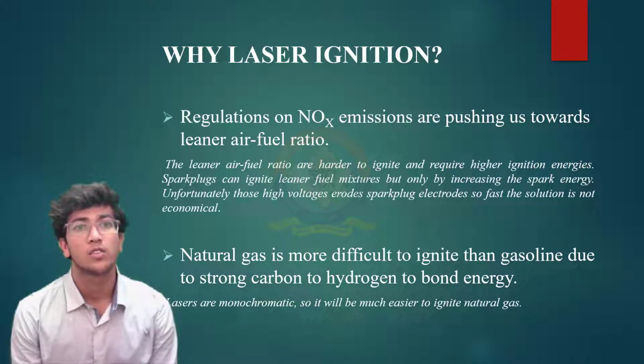Regulations on nitrogen oxide emission are pushing us towards leaner air-fuel ratios. The leaner air-fuel ratios are harder to ignite and require higher ignition energies. Spark plugs can ignite lean fuel mixtures but only by increasing spark energy. Unfortunately, those high voltages erode spark plug electrodes so fast that this solution is not economical.